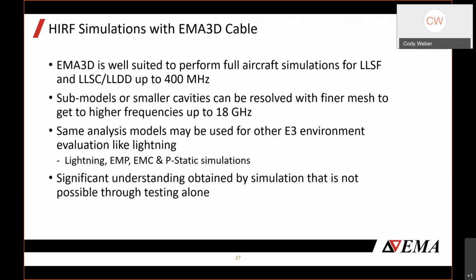So the tool that we use for these simulations is EMA3D Cable. It's well suited for these types of analyses, especially up to 400 megahertz. We have found techniques that are applicable to go to the higher frequencies if we use submodels with smaller mesh size. And the same model that I'm showing today that we use for HIRF assessment can also be used for lightning indirect effects assessment, EMP analysis, EMC characterizations, or P-static simulations. And really, the power of the simulation tools goes well beyond what is capable in test applications.